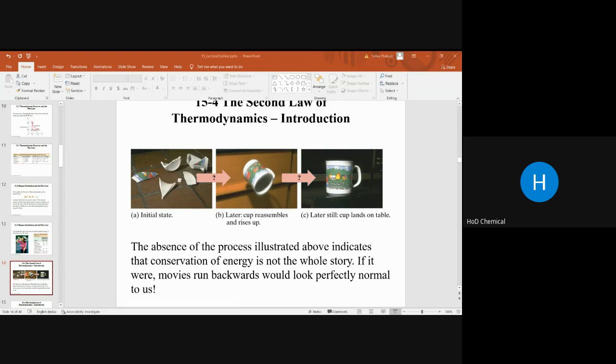For an ideal reversible engine, the efficiency can be written in terms of temperature. E ideal equals temperature high minus temperature low, divided by temperature high. With more simplification of the previous equation, it becomes 1 minus temperature low over temperature high. This is the Carnot efficiency, by using the ideal equations.